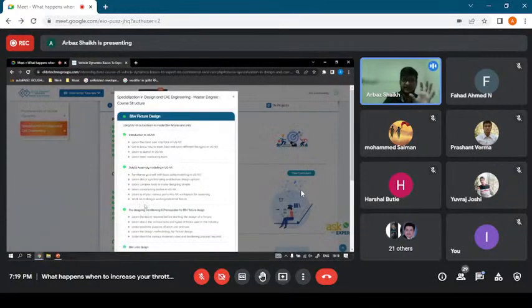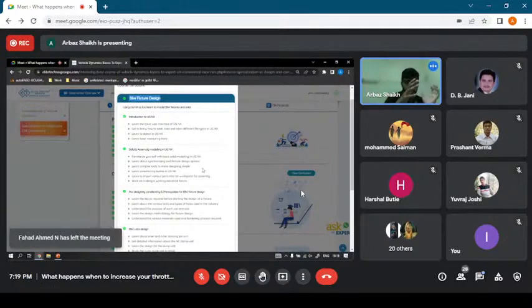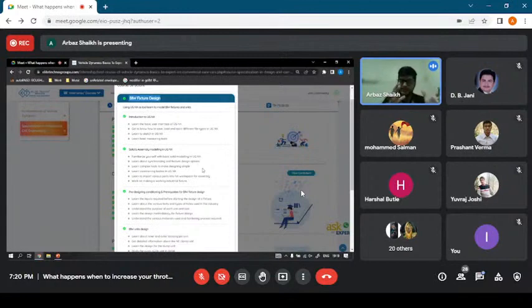Lastly, in the design part, you would also study the BIW fixture design. So now we have talked about the plastic design, we've talked about the sheet metal design, but when it comes to the industry, we have seen the assembly lines, right? They manufacture at a higher level or higher speed. In that case, they need automated lines and automated fixtures so that everything could be held in place and welded properly and made properly, right? For that, we make fixtures.